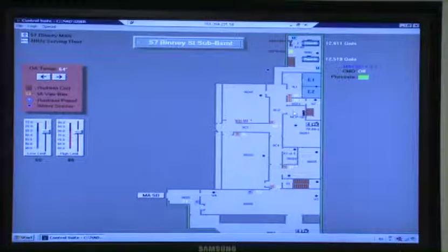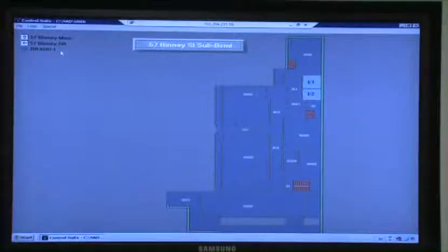Each floor has what they consider a UPS system on it for the controls. For every network switch going up, there's a UPS system on that floor. This is not developed yet, but every one of these will have a hyperlink to a UPS floor plate. It'll tell you where they are. Basically, it's the same floor plate as the AHU serving. It'll have the same kind of graphic, but it'll say UPSs on it. You'll be able to click on that UPS, and I'll show you what's going to happen.